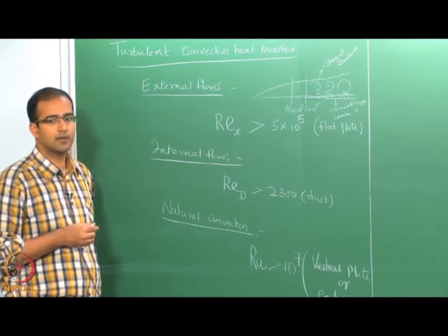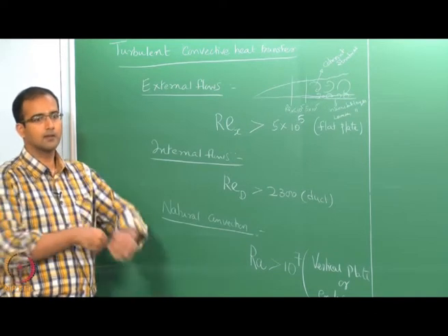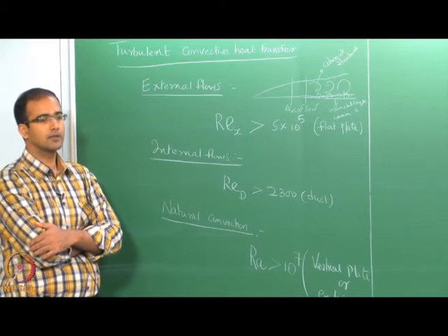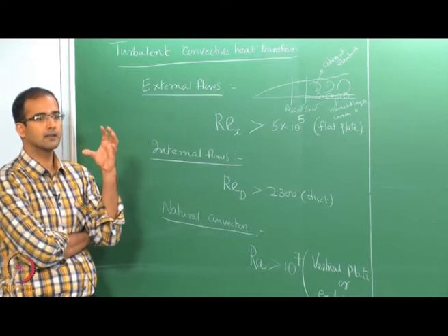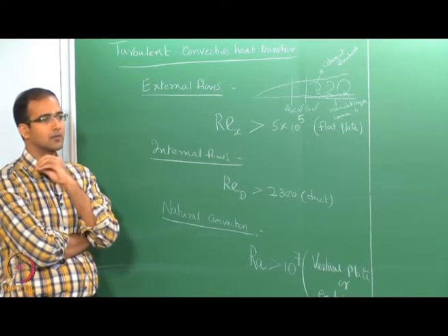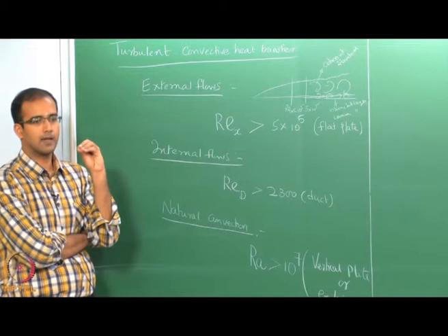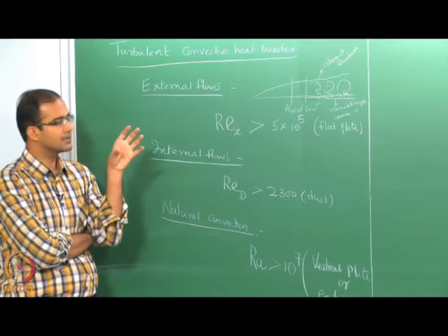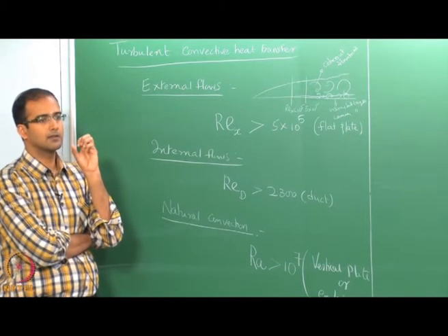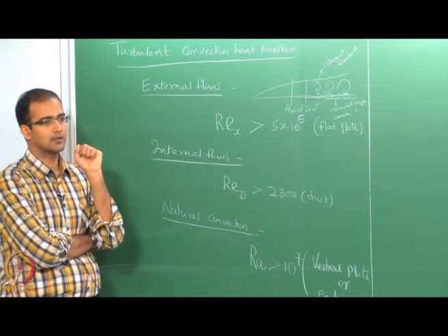So, in the case of a typical boundary layer profile, the effect of the wall is to damp the large scales, and finally the large scales cascade to smaller and smaller eddies, and finally it becomes laminar close to the wall, okay. Now, only in this laminar region you have the significant effect of molecular viscosity.